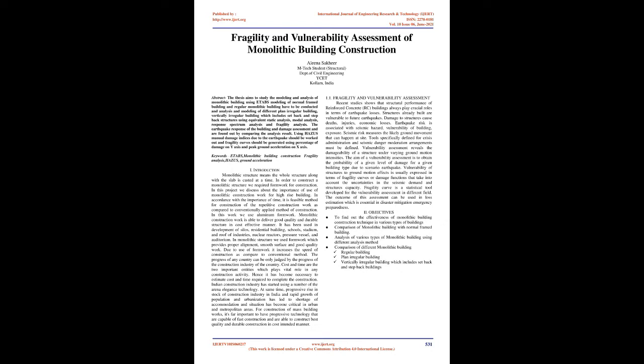Seismic hazard measures the likely ground movement that can happen at a site. Tools specifically defined for crisis administration and seismic risk mitigation arrangements must be defined. Vulnerability assessment reveals the damageability of a structure under varying ground motion intensities. The aim of a vulnerability assessment is to obtain the probability of a given level of damage for a given building type due to a scenario earthquake.